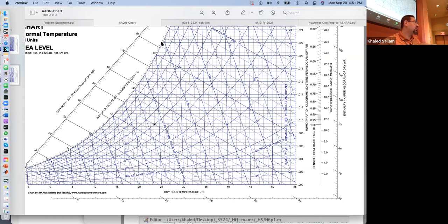Dew point. That's the dew point for that air. The air at 35 and 60% relative humidity, that is its dew point. If you go less than the dew point, then the air would come down like this all the way. So when you leave here, you leave at 100%. You are on that curve.